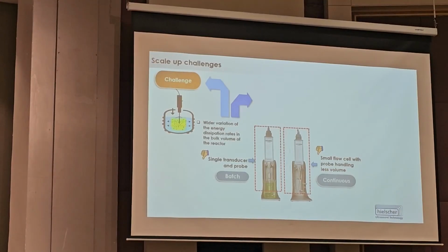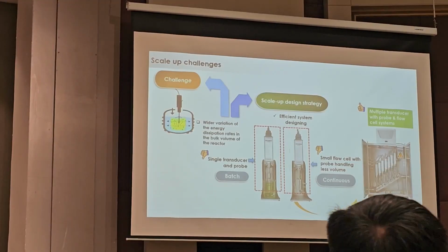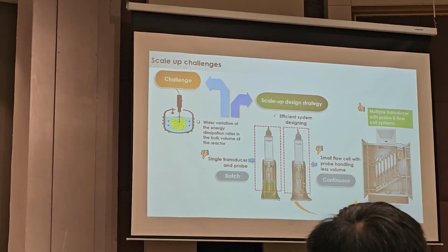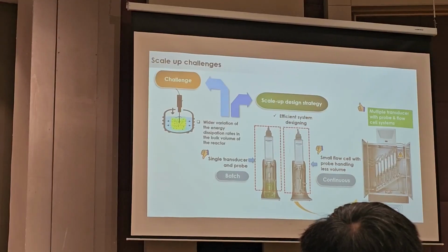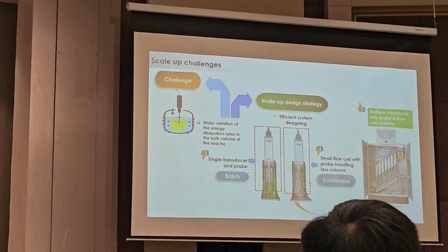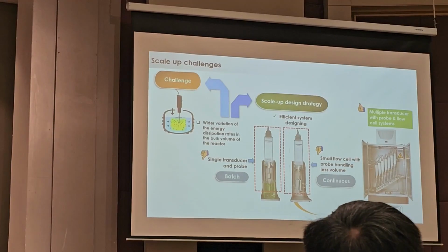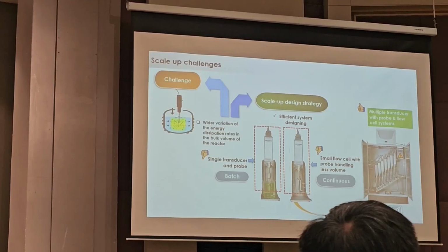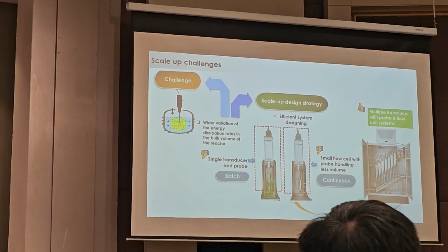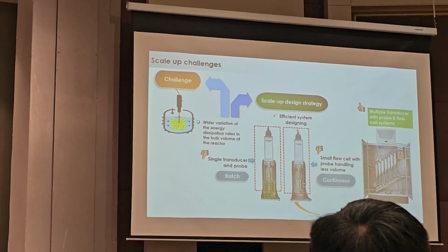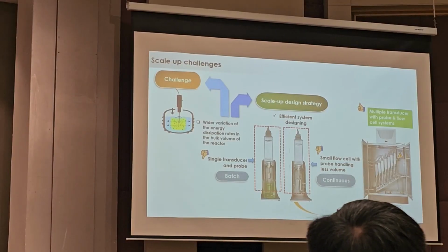So for scale-up operations, as in this case, you can see multiple probe systems designed, and if it's 5 minutes, that is the treatment time. You control the flow rate passing through this particular vessel, in a similar way flow rate and the volume, and accordingly you can make it a continuous process. It is always asked whether it's a continuous process or batch process. What we do, we can't make everything continuous. Fermentation takes 18 hours, it will take 18 hours. We can't make it continuous. What we can do is have multiple vessels to run the continuous business.